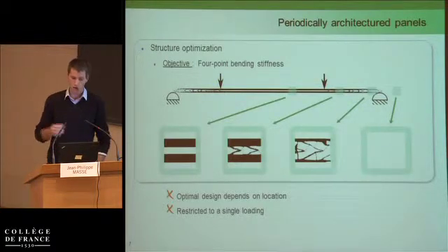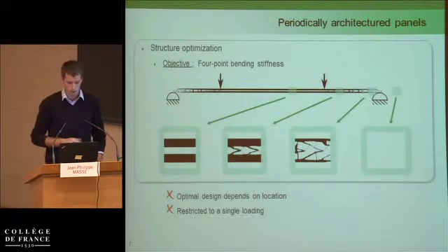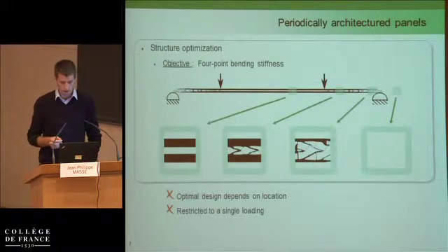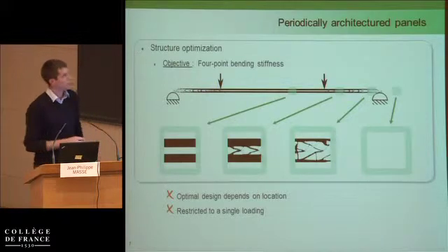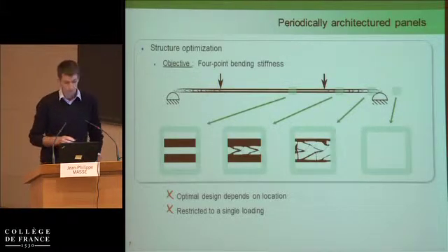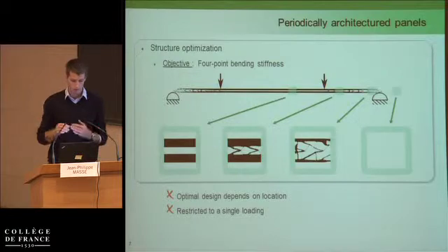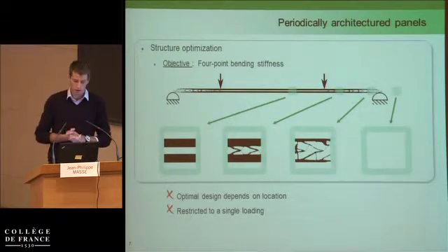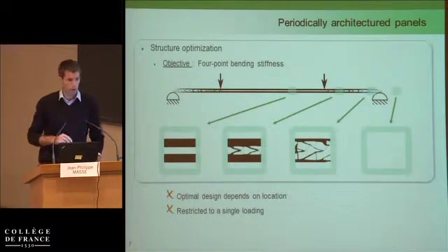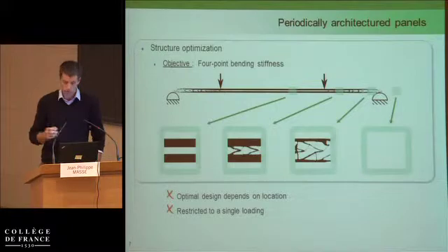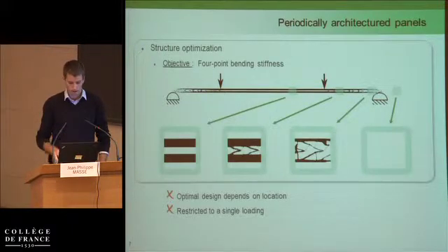And if we use shape optimization, I will talk about that later, on this project, we will find this kind of result, with matter in the center, where the solicitation is mainly flexion, we'll have matter on the skins, but in between the upper and lower indenters we'll have more a diagonal truss in order to provide shear stiffness.